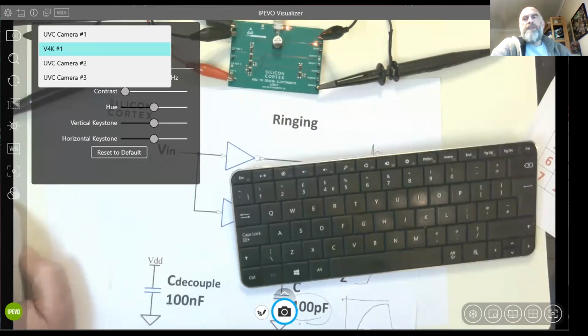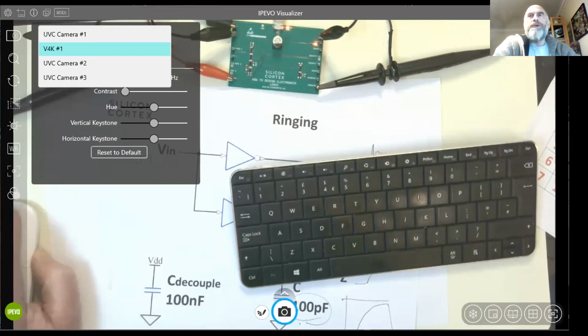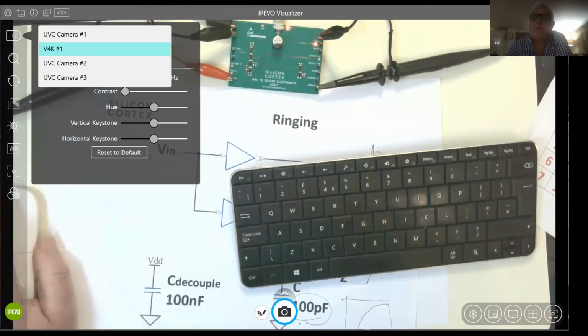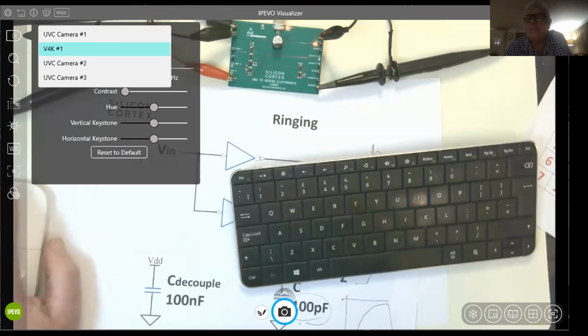Yes, but in this case, all that it needs to do is monitor the battery voltage. Say, if it goes under a certain level, turn the power supply on for a few minutes. If it drops down to 0, tell me. Yeah, you can get those. You can get voltage dividers and all sorts of little remote sensors that you can bring into the Pi. It's relatively easy to do. I've done it, and I'm not an expert.